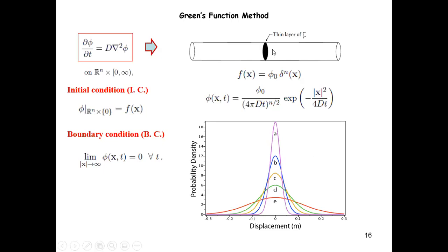Physically, this means that the carbon only penetrates a little bit into the surrounding region. You can assign the size of the region to be within, for example, the first sigma of this Gaussian, because this is essentially a Gaussian, so you can define a sigma. This is basically the penetration distance, roughly here.